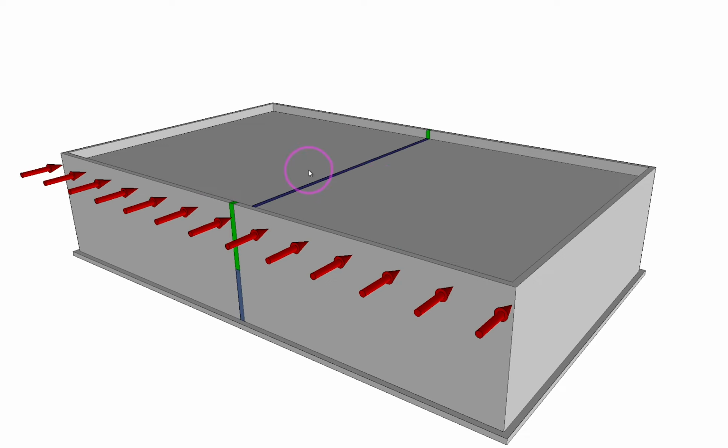this would be the floor plate, and wind load would be generated by half of the load above and half below. For seismic load, we would take the wall segment halfway below and halfway above plus the floor plate. So it's the same calculation, just one additional set of forces. So this causes the diaphragm to bend. The wall, whether it's a shear wall or a braced frame or a rigid frame, that becomes the stabilizing element in the same plane, the same direction as the load is going. And so that's where we go to with our calculations.